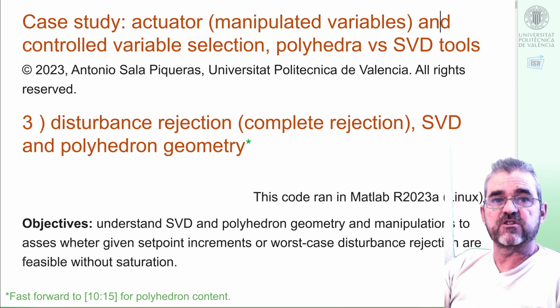So, if we first start with the geometry of ellipses, we must scale such geometry to transform it to the geometry of spheres in order to apply singular value techniques. As our singular value computations will assume that everything is symmetric, we need to choose the worst case disturbance as the scaling factor. So, we'll choose 0.8 and 0.65 as the smallest symmetric interval around the origin that comprises the actual increments. So we are on the conservative side of things. This is the disturbance scaling.